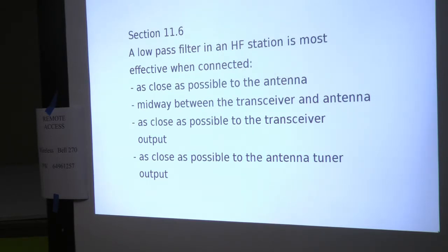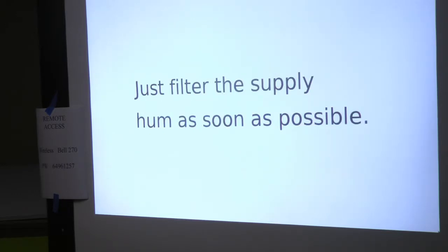I'd say number 3. Number 3, as close as possible to the transceiver output. That's the one I chose. Good, because that's perfect. Right on the money. Yep, just filter the supply hum as soon as possible, right?